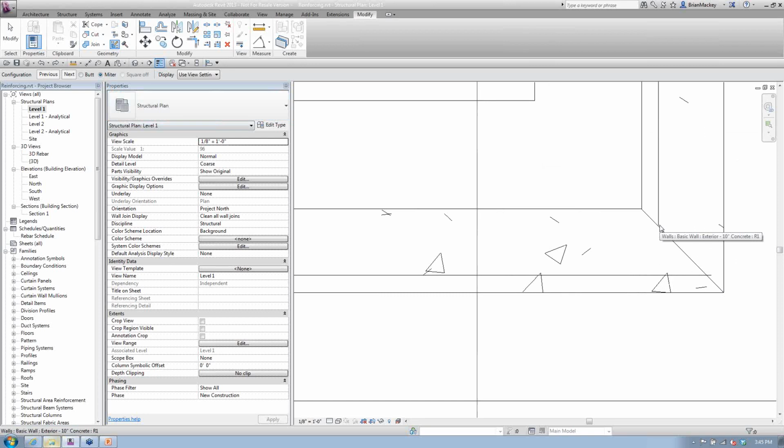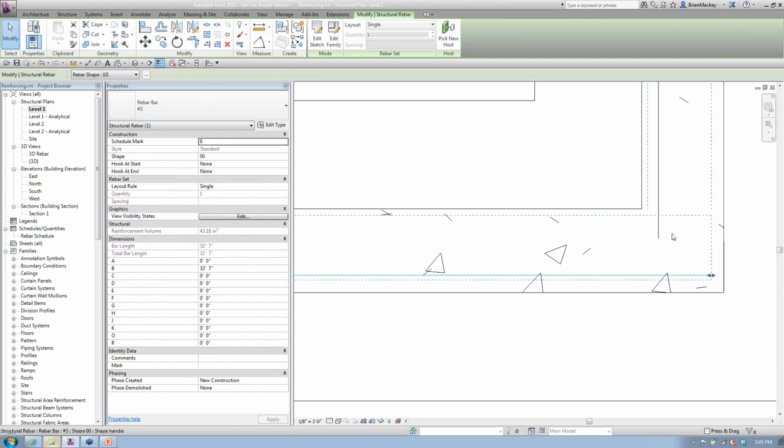Depending on your wall cleanups, if it's mitered, it might stop way short, or if it's a normal butt joint, it will determine which way that's going to go. And you'll also see if I do a next butt joint that this one got shorter and this one got long. So be careful with your wall joins as well as those cover distances of what's happening inside of there.